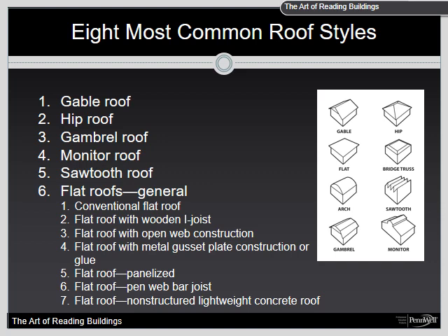When we look at hazards, what we're really concerned with is that lightweight construction, because they will only last 1/4 the time of conventional trusses as a rule of thumb. Again, because they're exposed to fire and heat, and they're only held together with metal and glue. And once they get heated, they lose their integrity and leads to failure.